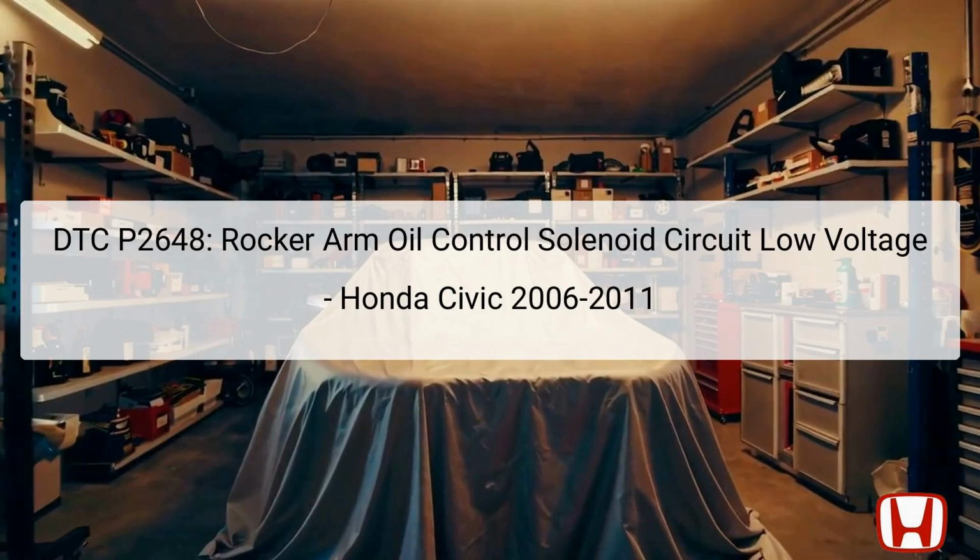The rocker arm oil control solenoid plays a crucial role in the variable valve timing and lift electronic control, VTEC, system of the engine. It ensures that the rocker arms are positioned correctly to optimize engine performance and efficiency based on driving conditions. When the circuit registers a low voltage, it could lead to improper engine functioning, reduced power, and potential engine damage. Identifying and resolving this issue is vital to restoring optimal performance. Therefore, diagnostic procedures must be followed step by step to pinpoint the exact cause and rectify it.